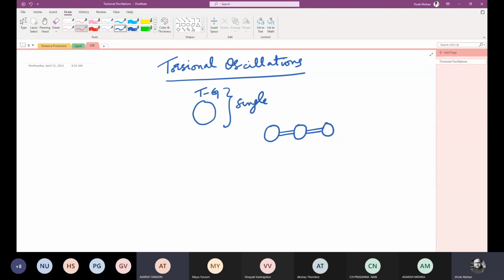Okay. So in reality, we have multiple masses connected with a single shaft. So this can be different turbines. Suppose I am writing here turbine T1, turbine T2, and this is a generator. So this is a 3-mass system having 2 shafts. So in steady state or in equilibrium condition, or without the effect of a disturbance on any of these masses, they have the same speed. All these masses have the same speed, which is the synchronous speed of the generator.